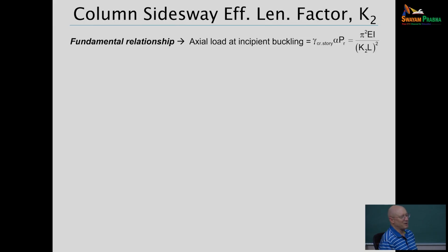And that's where I always tell my students at Georgia Tech, the effective length method is a misnomer. It's the buckling analysis-based method. It's not the effective length method. With that said, let's talk about getting a side sway effective length factor. Whatever you're doing, non-sway, side sway, it really just comes down to what I'm showing you at the top of the screen. You take your axial load in the member at buckling,